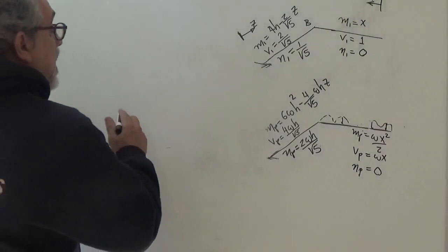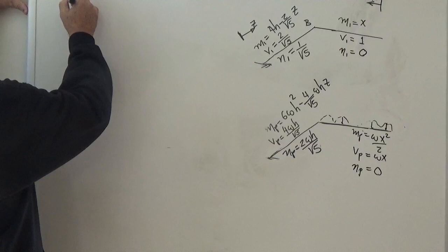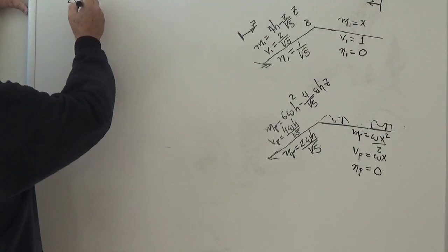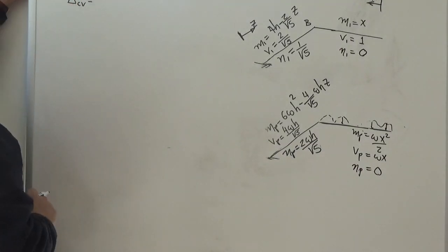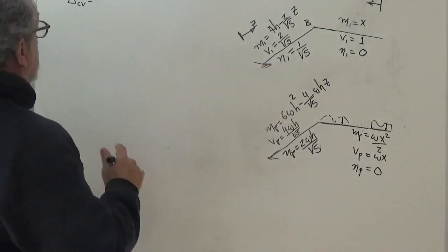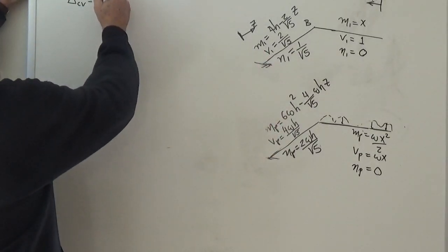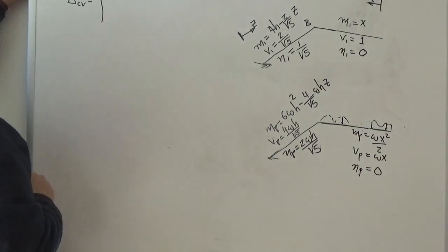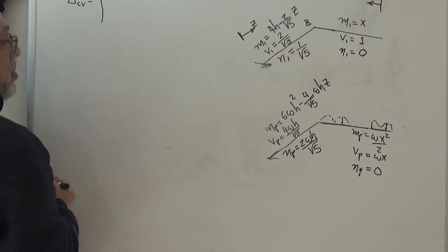So we then say here, delta C in the vertical direction is equal to the integral of M1 MP, the integral of N1 NP, and so on, right? So let's begin with bending. Could organize it per bar or per bending. Let me do it first bending, then axial, then shear.